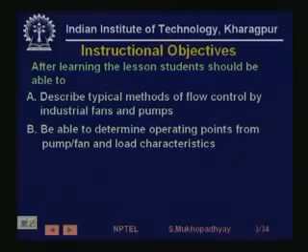Now, firstly, when we connect a machine to the pump, what is the amount of flow that is established? That depends on the pump characteristics, that depends on the machine characteristics. So, we are going to see how, when you connect a pump or a fan with a so called load, the operating point is established: what will be the pressure, what will be the flow. It is actually much like establishing an operating point when you connect a battery with a circuit or a load, right. So, we are going to see that, and we will see that